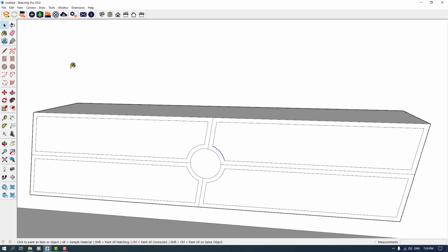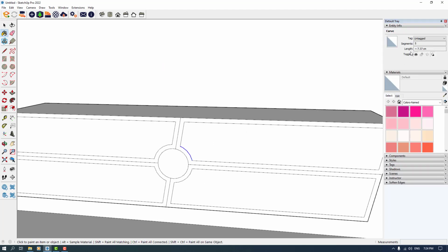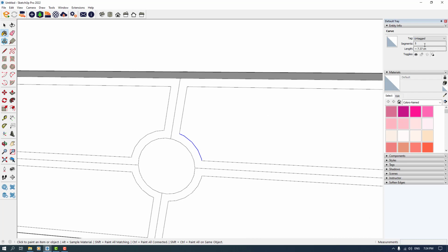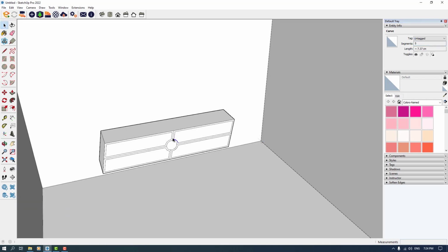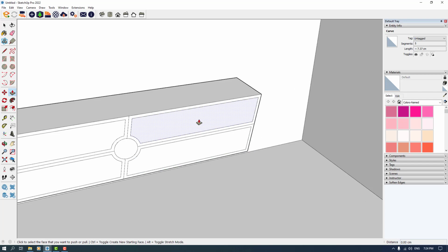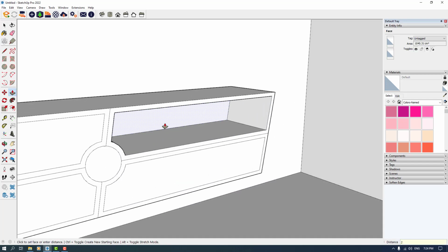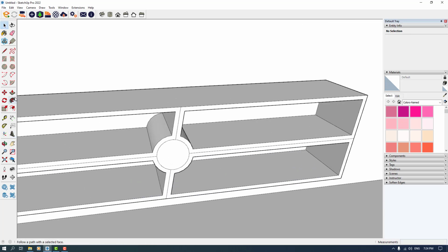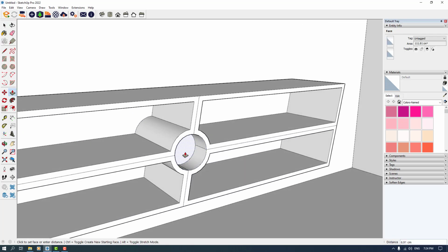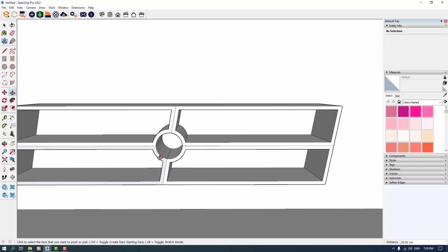I come to the material library, Entity Info. I'm gonna increase my segments from 5 to 10, actually something like that. Alright, now it's much better. I press the extrude option like this, extrude about 28, 28, 28, like that. And another for this place, 28 again.